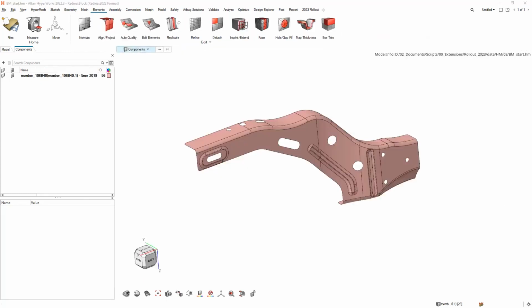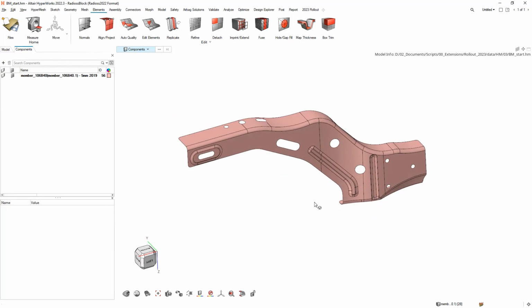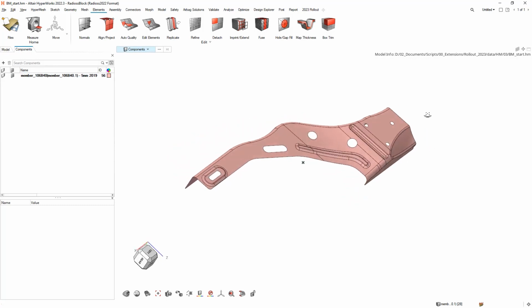So we've seen how powerful and flexible HyperMesh can be to give users full control over the detailed meshing and modeling with our tools. But to take advantage of these more efficiently, HyperMesh has also embedded these tools in batch that automates a lot of these common and repetitive tasks. So I'm going to start with the geometry on the screen. And some of the common things we've seen are things like suppressing edges, imprinting washers, those kind of things.